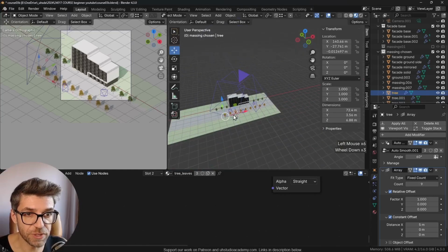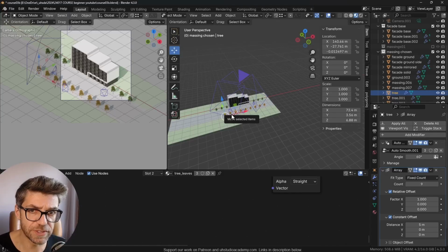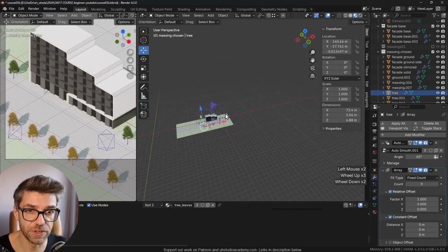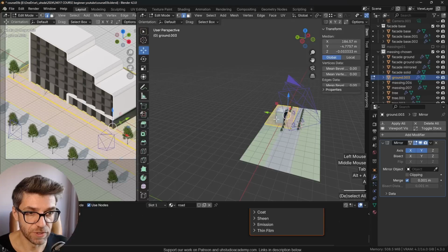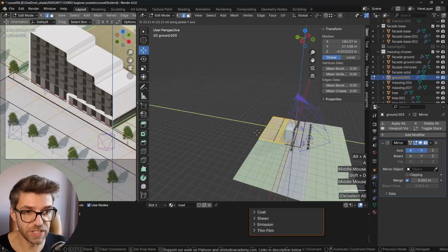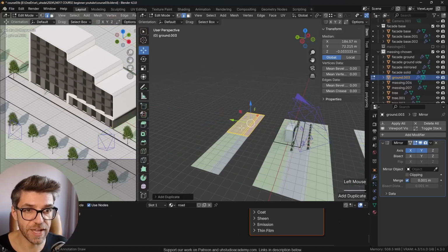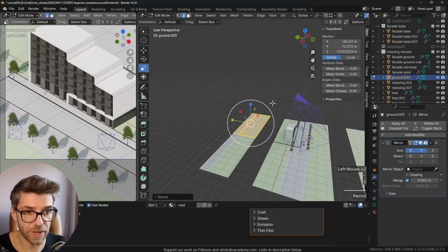Now, because we are preparing this scene with all its context a little bit, so this is contextual and rendering, we can visualize different facade options for our building over here. We might as well finish the job by, first off, duplicating this, Shift D to duplicate it, hold the middle mouse button to lock onto the Y-axis, and now let's go to scale, and we want to scale -1 along the Y-axis.